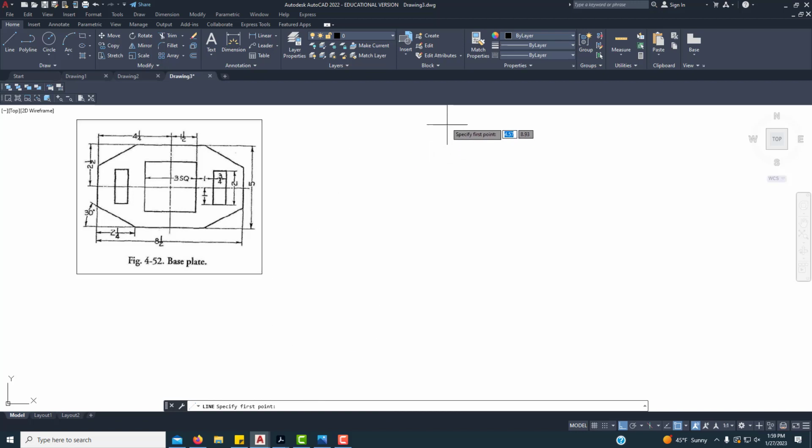So the first thing we're going to do is click one time to start a line. And I'm not really measuring anything. Right here it says it's about 6.5 inches. That's fine. My drawing height was 5 and the width is 8.5. So I want to have about 6 inches, 6.5 inches is fine.